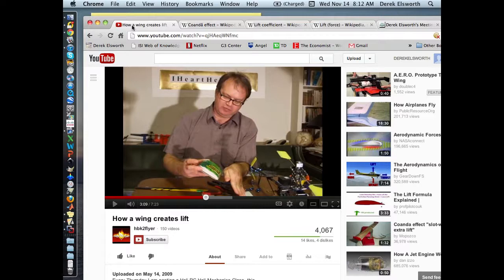If you look at forces on structures, I mentioned the other time, Alan Davenport was a professor at University of Western Ontario, which became kind of a world-renowned place to do wind tunnel studies on downtowns of cities, to be able to look at the forces on structures, new structures that you might build in terms of wind forces, which of course are affected by the other buildings around them. And so you make a wind model and you scale the experiments to be able to figure out exactly what those forces might be, whether the wind will knock the windows out, whether the people walking in the canyons at the base of those buildings will get blown down the street, etc. And so experimentation is a big part of some of this work.